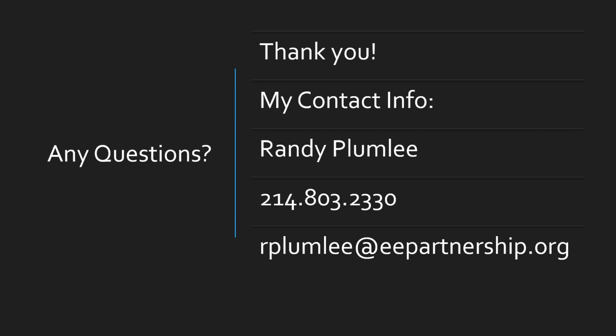If it's an all new, brand new 25,000 square foot addition, like they're adding another warehouse attached to an existing building, but it's 25,000 or more, in my opinion, everything in that addition should now be adhering to the energy code. That means energy monitoring, all of that needs to be done. But it gets confusing if you've got existing chillers, water heating, HVAC. If they're existing, you really can't make them meet the new requirements of the energy code, even if it's now part of the new addition. It's just a tough call, and it's going to be down to the building official to make that decision.